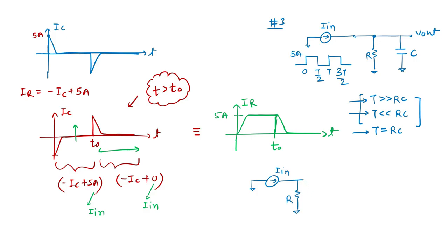It is the resistor. So there is a one resistor, one capacitor system. Let me open my capacitor, and I want to see the R equivalent across the capacitor. So what is the R equivalent? When we calculate the R equivalent, we make the independent source open. So the only thing visible to me across this cap is R.